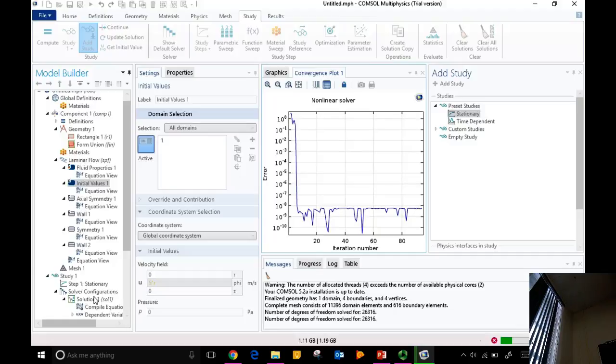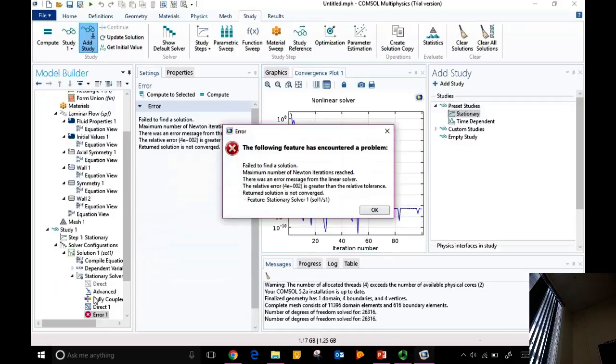Because this velocity of v5 equal to 5 times r is not the right profile. I want this to be 1 at the inner cylinder, and I want the other one to be 0, right? So I need to make this v5 equals a r plus b, and figure out what these two boundary conditions are. When r is 0.2, it's 1: 1 equals 0.2a plus b.